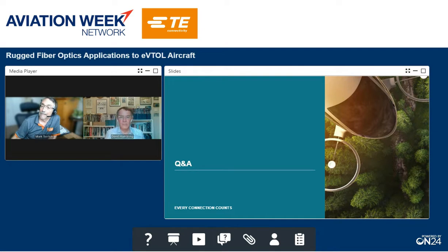Right, certainly. Another question here. What trends are you seeing specific to the electric vertical takeoff and landing market? I think the trend we're seeing right now, from a fiber perspective, and this is very limited data and it's very early days, and there's lots of manufacturers looking at lots of different ways to attack this problem, but it seems to me that there are two ways fiber's going to find its way into these applications. One is driven by weight and the EMI concerns around the propulsion systems, where the network will fundamentally be fiber. And by that I mean fiber into the interfaces on the LRUs and into transceivers that will be embedded in those flight controllers, which may become new flight controllers that have to be certified, that might not have any previous experience in ComAir.